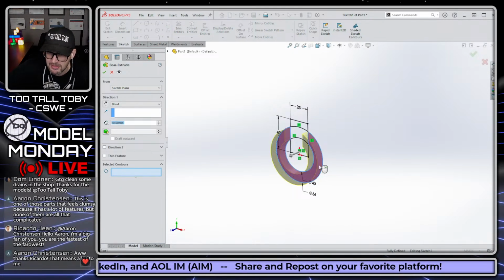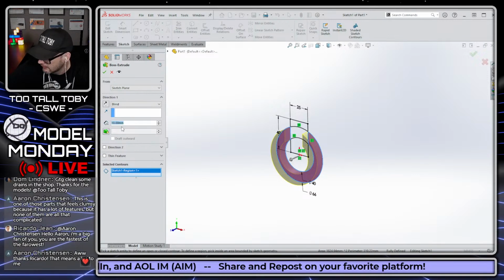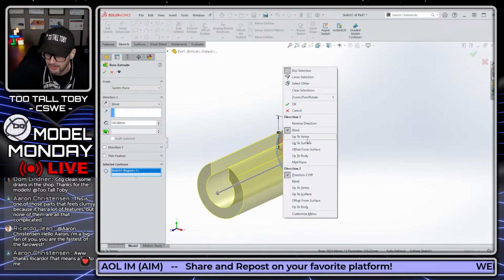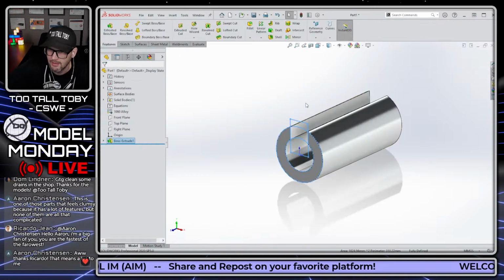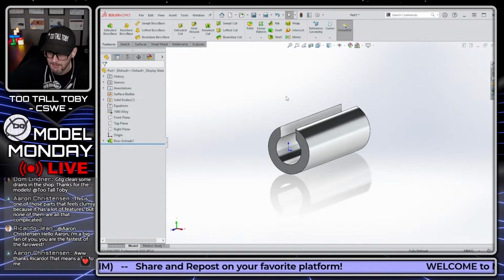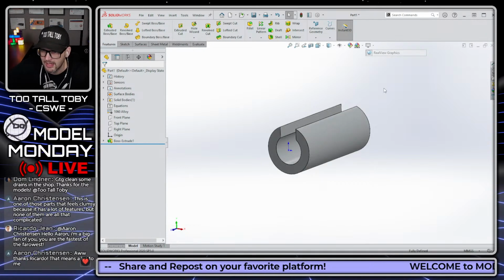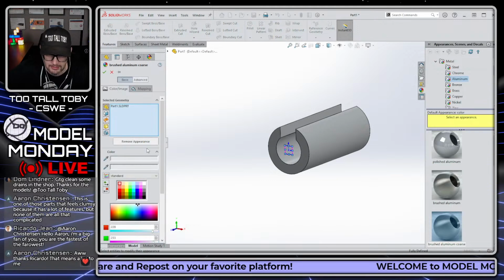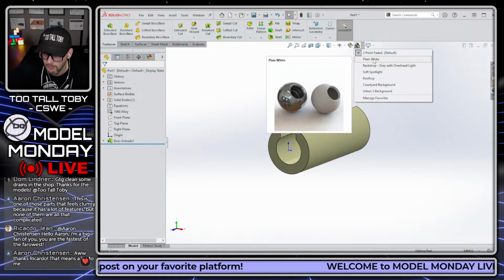So now we can take that geometry, and we can choose to extrude it. This is going to go out to a depth of 140 millimeters, and I'm going to right mouse button in the background and say reverse direction, and then right mouse button again. And there is our first feature for this model. So now for our second feature, let me change the color of this thing just to make it a little bit easier for everybody to see some of the features that I'm adding. Make this a plain white background.